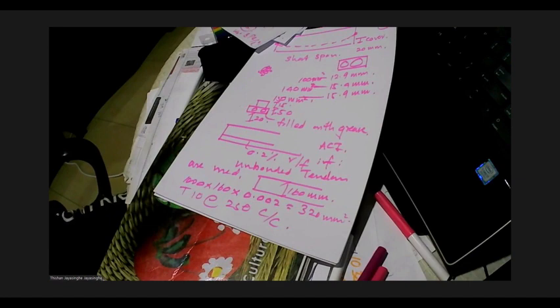But with 160 millimeters in reinforced concrete, you need a lot of reinforcement like T12 at 150 when the spans are about 7 meters. Whereas in this case, you need only nominal reinforcement, T10 at 250. So the saving is substantial. And you don't need a lot of top steel, only the requirement of top steel.